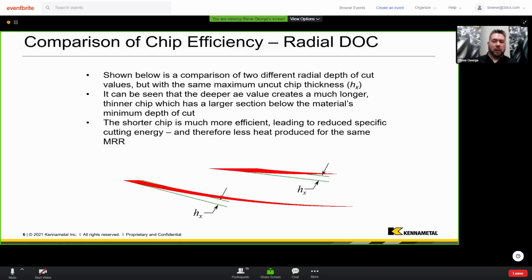The other thing that comes into play, and this is a lot less evident on the surface, is something I really like researching: specific cutting energy. I have tons of dynamometers, Pro-Micron Spike systems, strain gauge systems, all sorts of stuff. We make a lot of cutting force measurements, and with those we can get into specific cutting energy. So how much energy does it take to remove a certain amount of material?